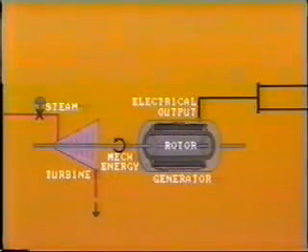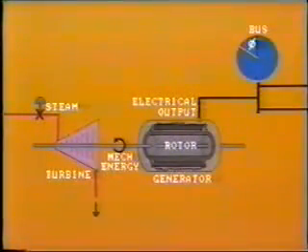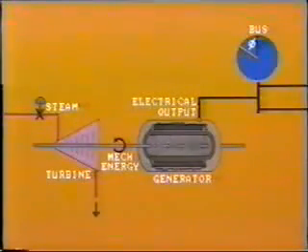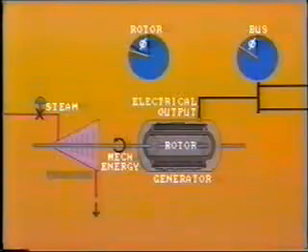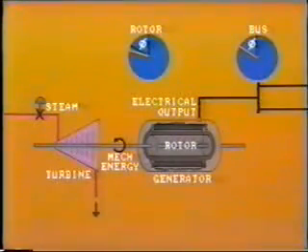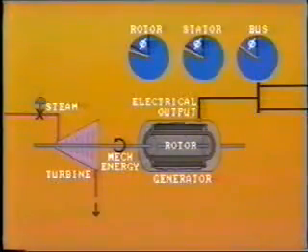In the previous segment, we saw that the voltage phase displacement between the two ends of a transmission line determines the amount of load transfer that can take place. Actually, the phase angle of the voltage at the sending end bus is determined by the physical angular position of the generator rotor, which is being driven by the prime mover, say a steam turbine. As the rotor accelerates and moves ahead, so does the corresponding voltage, which is generated in the stator windings.